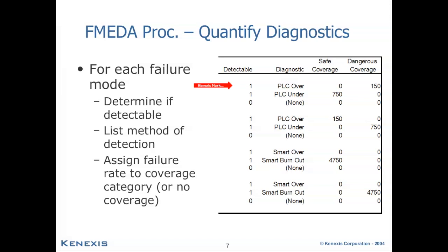All we need to do is program our PLC to detect that the milliamp input to that I/O channel is significantly in excess of 20 milliamps. How much in excess of 20 milliamps is going to be a function of which equipment vendor we're talking about. But in general, we just call that a PLC over range, and a lot of PLCs have this built in automatically. It simply generates a bad PV.